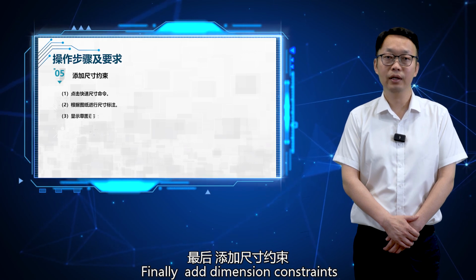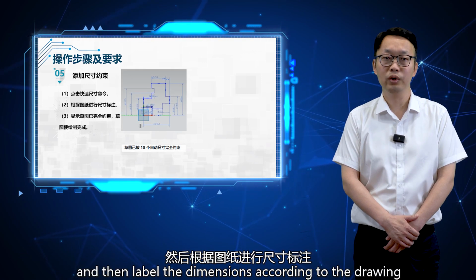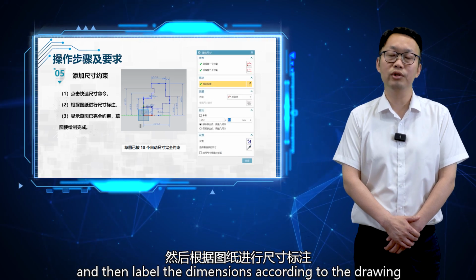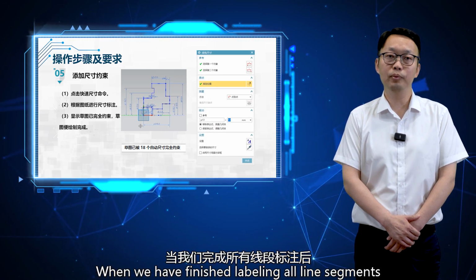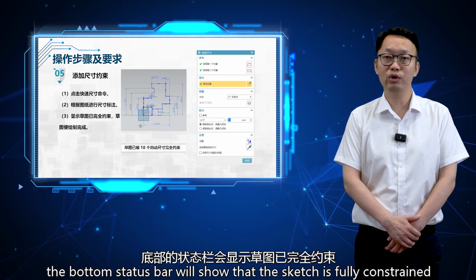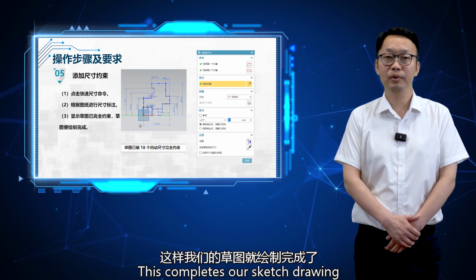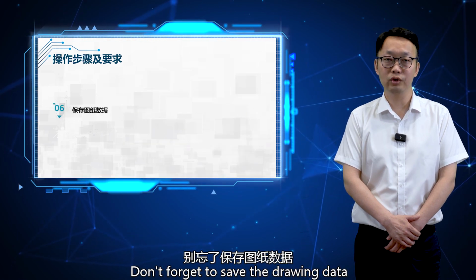Finally, add dimension constraints. Click the Rapid Dimension command and then label the dimensions according to the drawing. When we have finished labeling all line segments, the bottom status bar will show that the sketch is fully constrained. This completes our sketch drawing. Don't forget to save the drawing data.